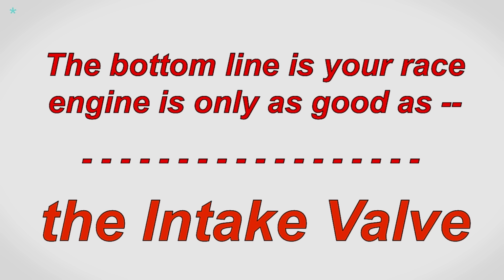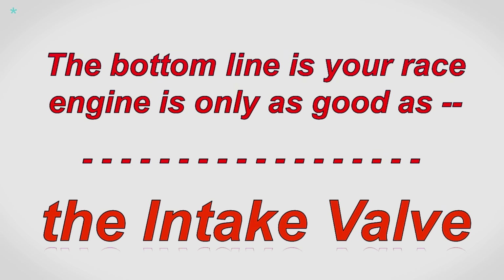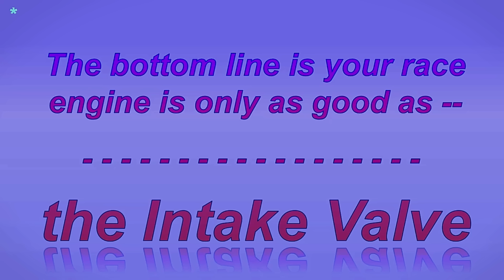Now, the unfortunate thing here is that during the delayed closing of the intake valve, the piston's coming up the bore. So there's a propensity for whatever was drawn in to be pushed back out again. We don't want that. We want a valve which, when it's open, flows well going in, but not very well for the air to reverse and go out. That goal is better achieved by making sure that we deal with what we call reversion, and that's what we're going to talk about now.